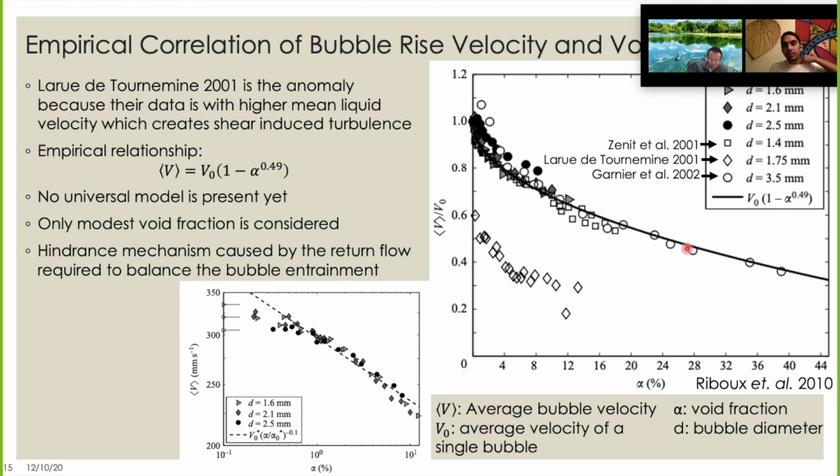So this is planar PIV. They're only looking at one particular plane. And from my experience, you can mask out the bubbles. You can identify the regions where the bubbles are, mask them out for every frame, and then analyze the flow around it. That is how it is done.